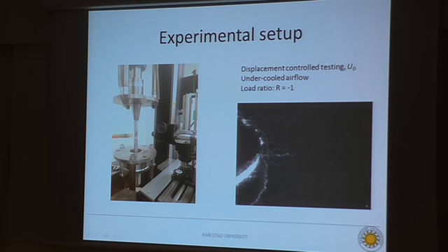What we are doing during the experiment is trying to get the crack initiation from the beginning by increasing the load in steps until we get the crack initiation, and we will try to stop it after approximately 0.5 millimeter, and then change the load and keep the experiment running in intervals of 0.5 millimeter, where we change the load after each step.